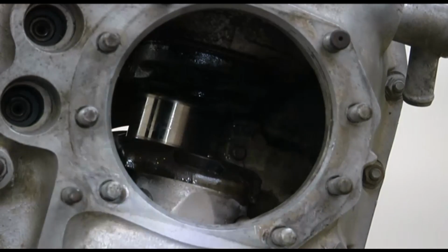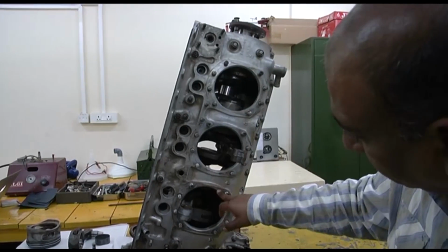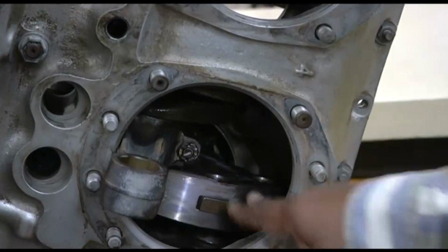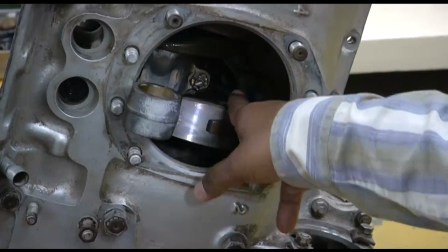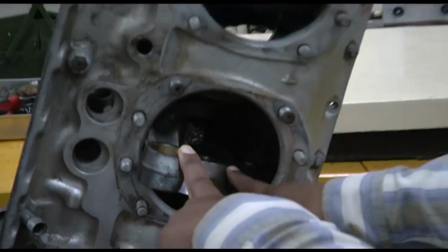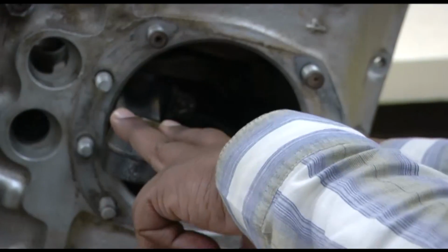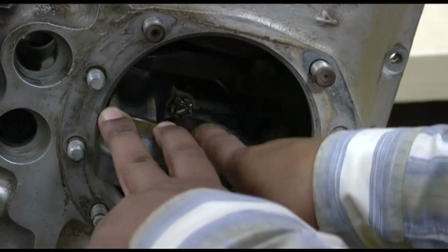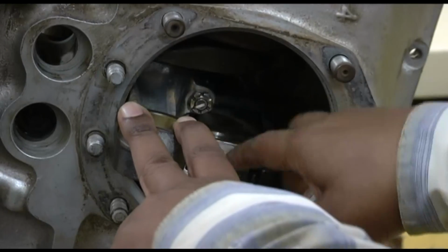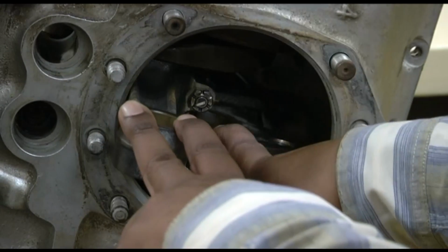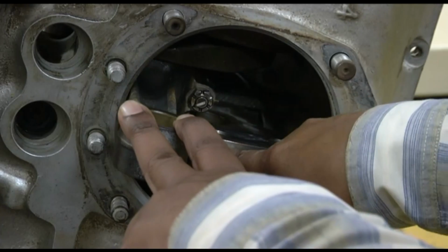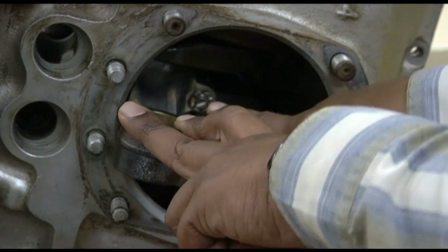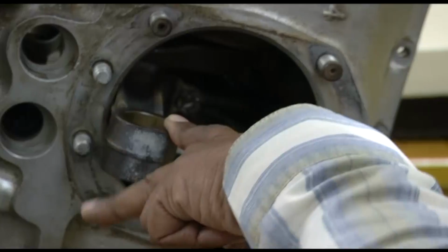This is your crankshaft timing gear. So this is your crankshaft. Here you can see we have also studied in the class about the dampers to dynamically balance the shaft. So this is your dynamic damper here. This is your counterweight which is attached to the crankshaft so that your crankshaft is dynamically balanced. On the counterweights you have the holes in which you have the 2 spool pins. These are the spool pins here to provide a pendulum effect so that your crankshaft is dynamically balanced. So this is your counterweight with your dynamic damping. We have seen it in the class.